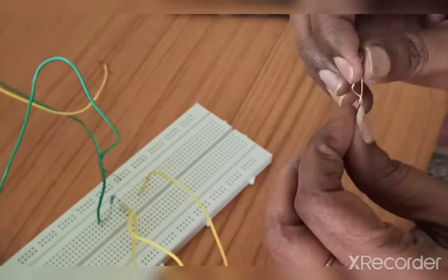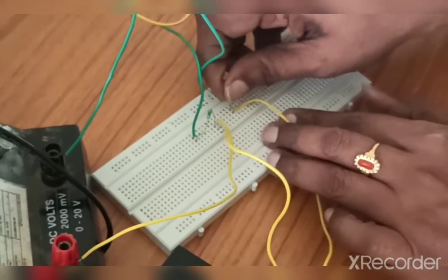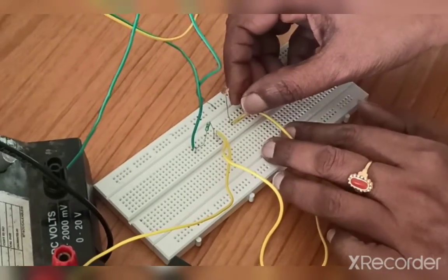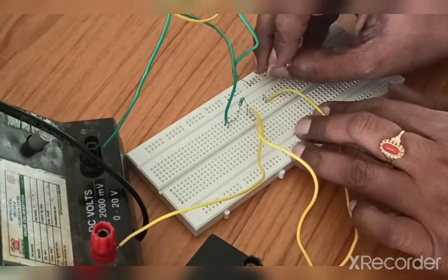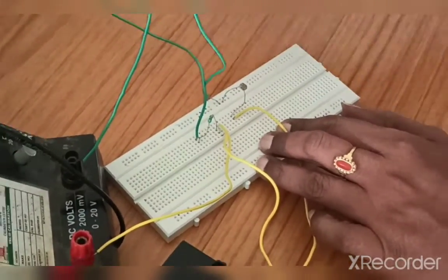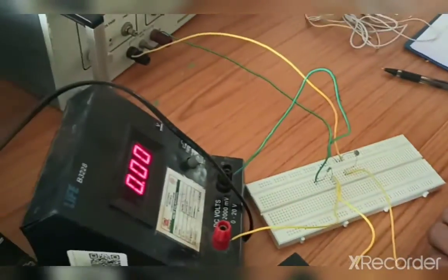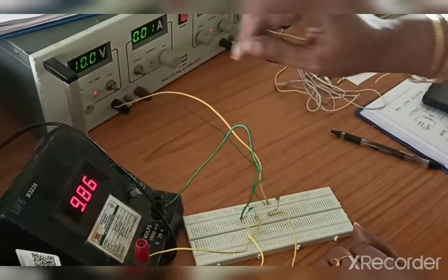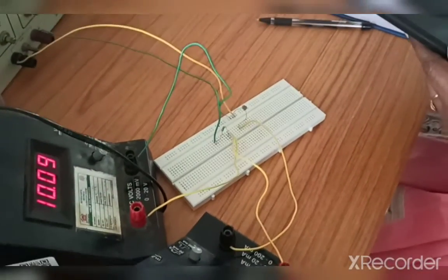We have to choose the RC value greater than T so that the capacitor does not discharge during the positive half cycle. So RC is equal to 10 times T, that is RC is 10 milliseconds, and assume that C is equal to 1 microfarad. From that we can find R is equal to 10 milliseconds divided by 1 microfarad, which is 10 kilo ohm.